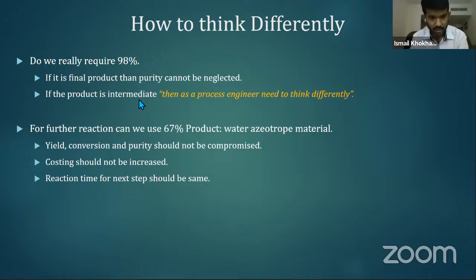in the first low boiler cut. So when 2.5% to 3% they were not allowing it to get into the incinerator. How is the management going to approve your design with 8% loss just to have a single distillation column? And also you should keep in mind that a distillation column is a one time investment, and that investment needs to be very clever.